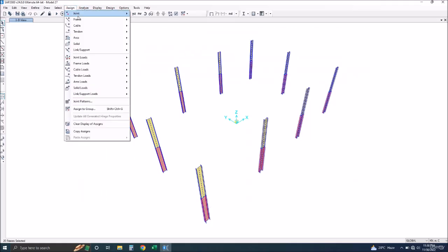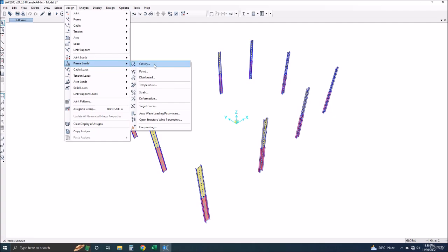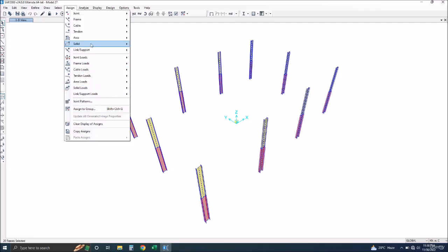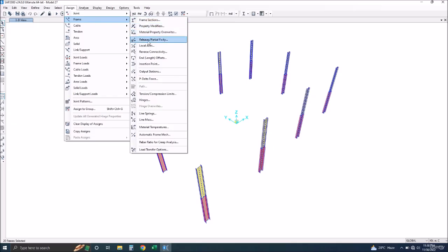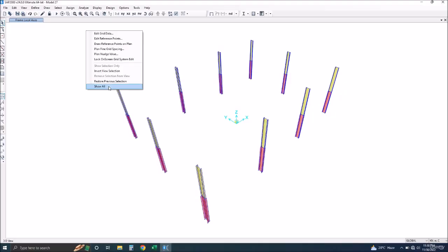Let's rotate the columns. As we have the shear wall as well as the columns strong dimension aligned in the same direction and we have to strengthen the y direction. So we'll use the columns to strengthen the y direction. Make this 90 degrees. Now